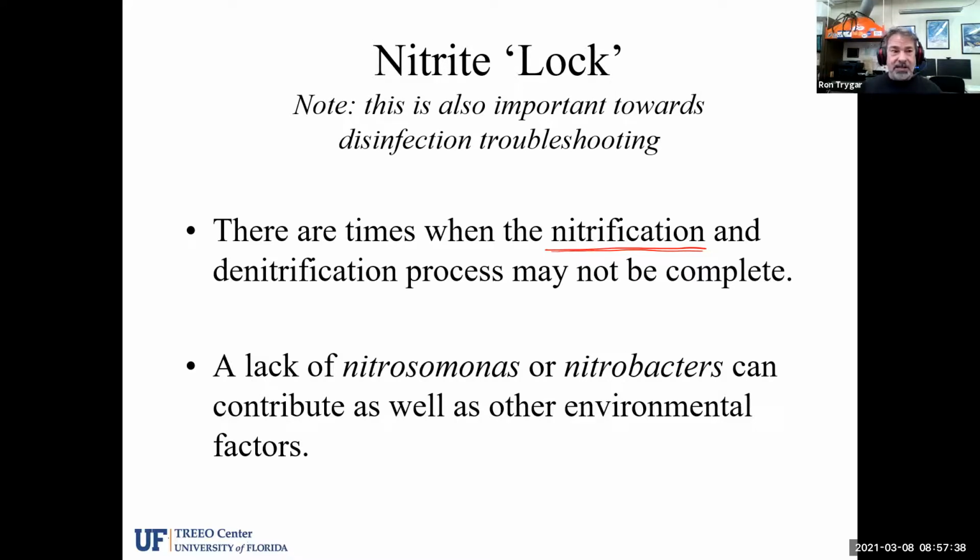So it's more towards nitrification where we don't have enough time. It's a little more prone to be seen in, say, the Ludzak-Ettinger processes or basins where we have a flow right straight through the process without a secondary anoxic basin to polish off any of the nitrate or nitrite that didn't get quite converted.